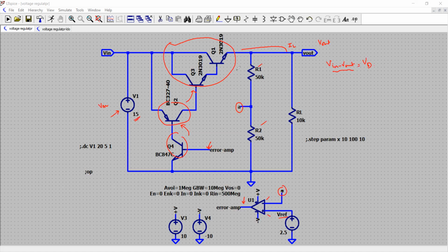And we said that in this standard regulator the overdrive voltage should be about 3 volts or more. And we said that we wanted 5 volts in the output. So this is sufficiently greater than the output required. So 5 plus 3, we want 8 volts minimum, but we have this 15 volts, so it's essential.